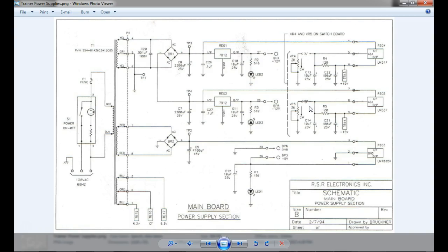Okay. Here's the actual main filter. These are small filters. They give you the size that they want you to use on this, just to prevent the thing, when it regulates and it's trying to move around, from getting really big. This is a 22,000 microfarad, 25 volt capacitor. And we got the same thing up there on the plus 12. That's a 7812. That's a what? 12 volt regulator. So we're not actually seeing this guy discharge. We're seeing this 10 microfarad discharge.